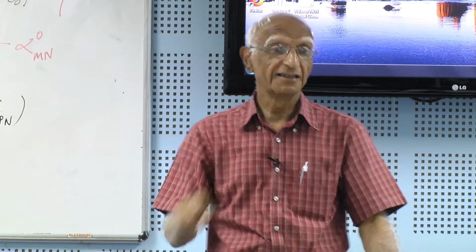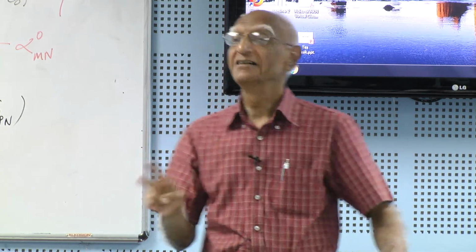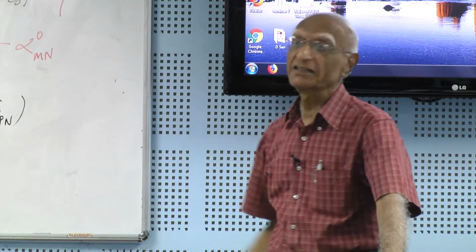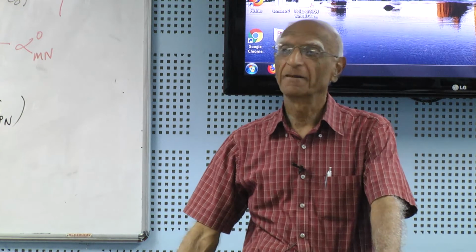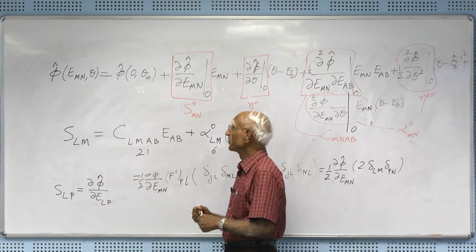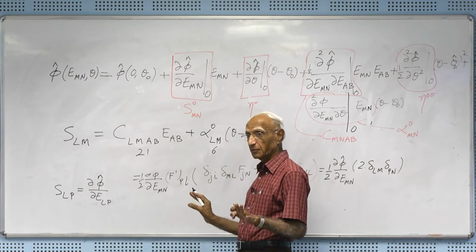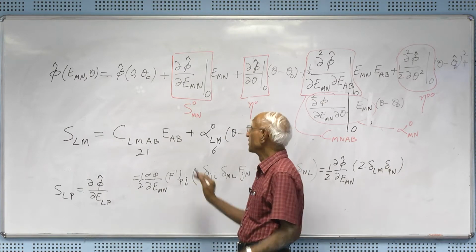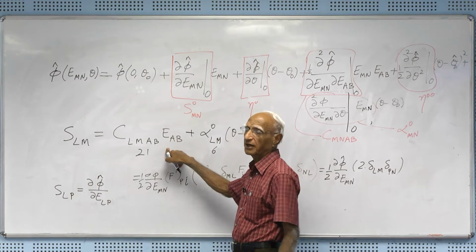And that we have assumed that the free energy can be expanded in terms of Taylor series. Otherwise, we have to find the free energy function. So that will give us the simplest nonlinear elastic material, or simplest material valid for finite deformations.